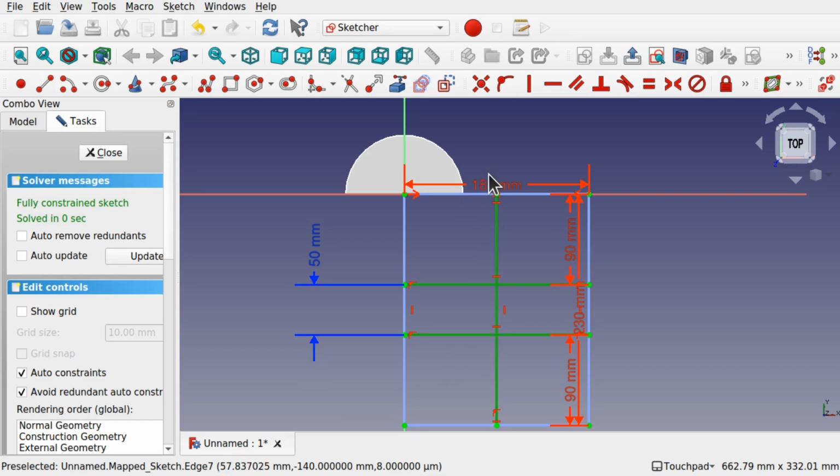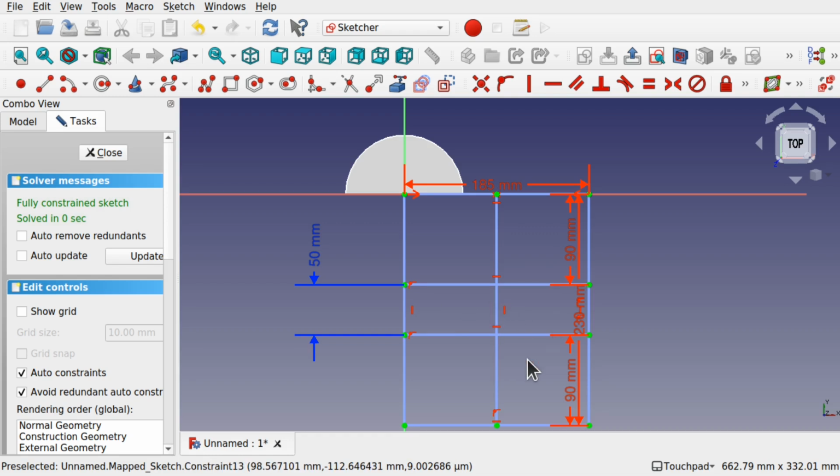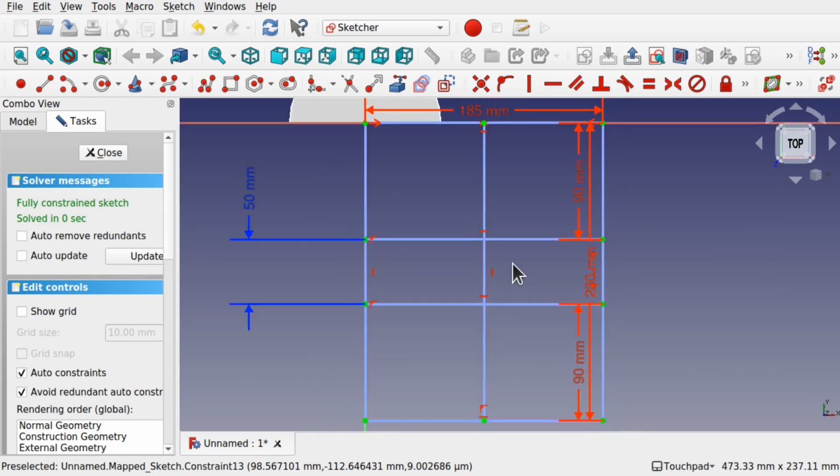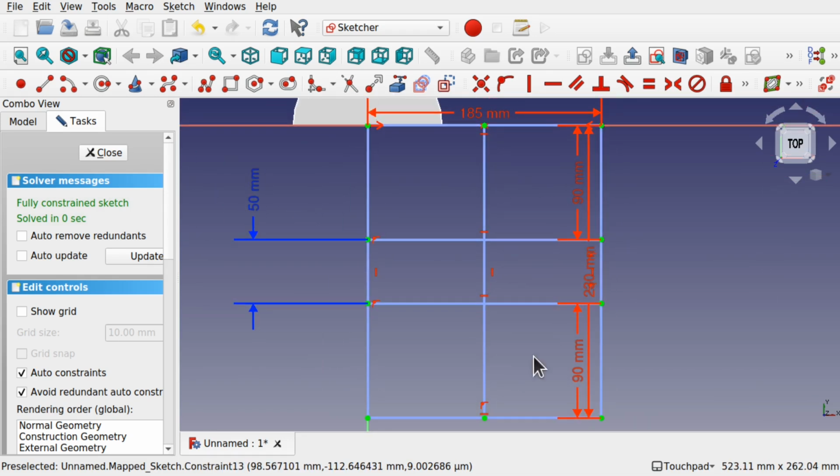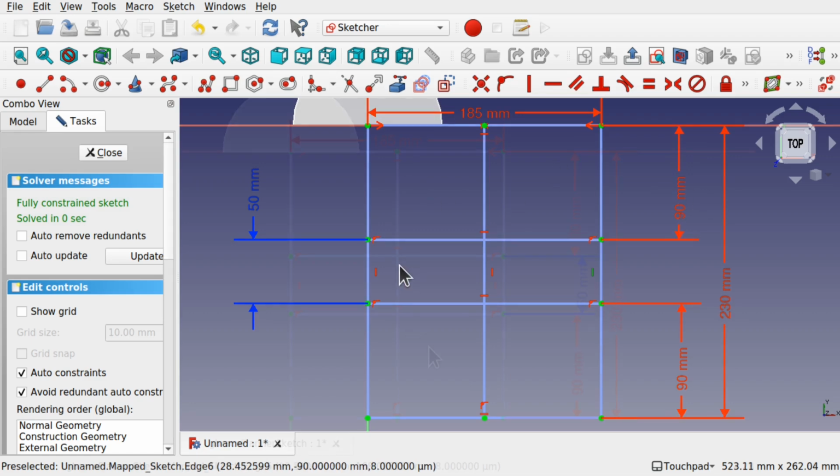We've got all those selected. Well, I don't have to control click them, just select them. Change those to construction. Now we've got something to go on. I'm just going to be sketching in this section over on the right hand side. Let's just pull these out of the way. I could keep all my dimensions actually to the right and then sketch in the left.